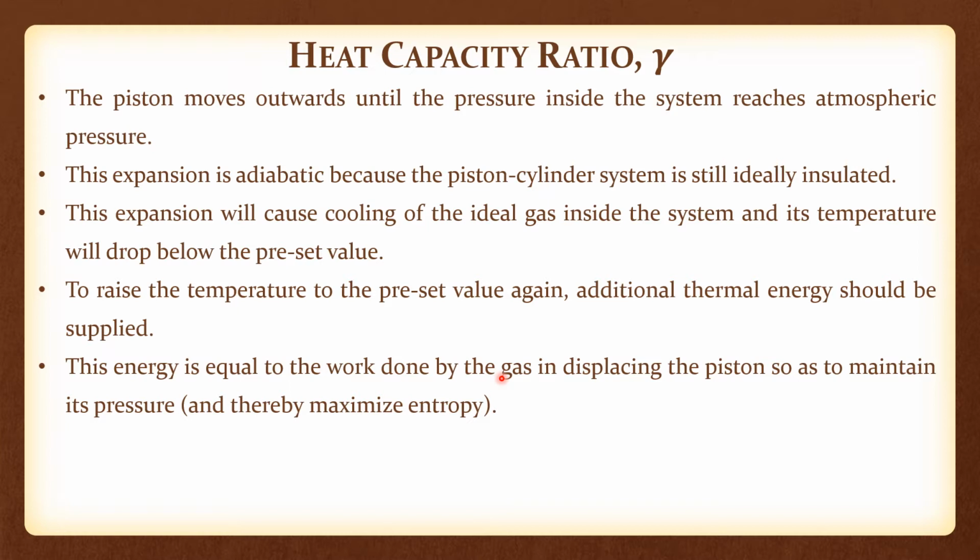So how much cooling has happened? Why did it happen? Basically, the gas did work to move the piston to the new position where there was mechanical equilibrium. So that energy was taken from the gas, and since the ideal gas only has kinetic energy, its temperature has to drop. So if you were to bring the temperature back to the preset value, the new state of equilibrium is where the pressure is constant, not the volume. The volume increased, isn't it?